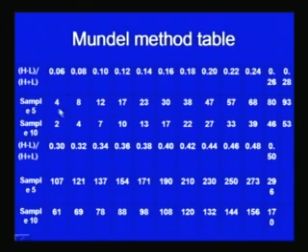In the same way, for different values of this ratio and different sample sizes, the number of observations required can be seen directly from the table. Another example: if the ratio value is say 0.4, then for a sample size of 5 readings, the number of observations to be carried out will be 190, while if the sample size is 10 readings, then the number of observations will be 108.